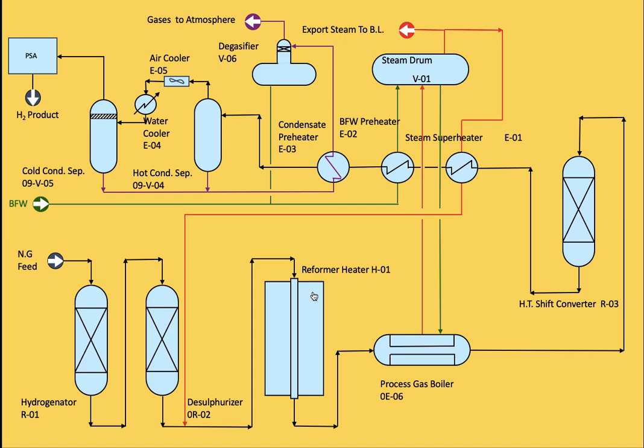Okay, what is the steam to carbon ratio here? Between 2.5 to 3.5. The minimum is 2. You should not go lower than 2 as a steam to carbon ratio, and I think there are 3 points related to this ratio. Okay, a high steam to carbon ratio prevents carbon coking on the catalyst tube and improves the catalyst life, but increases the operating cost. When you increase the steam to carbon ratio, you improve the operating parameters related to the unit, but one side effect is increasing the operating cost.